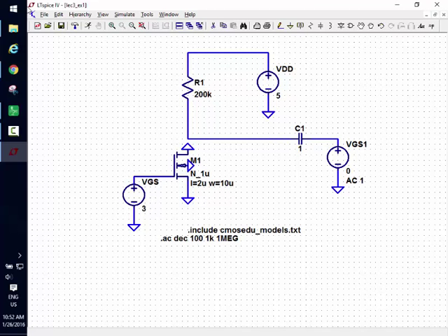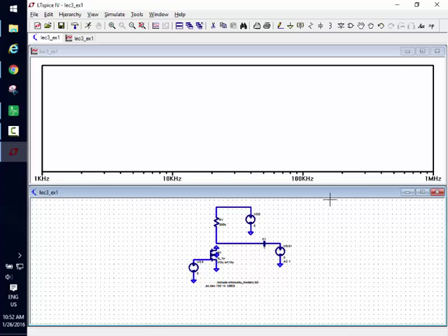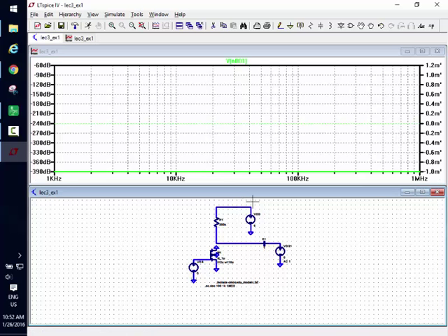All right, any questions on this circuit? What's that? Yeah, I'm going to leave the transistor out just to show I get 5 microamps flowing through here. Okay, so I hit run. First, I'm going to show the magnitude of the voltage here for AC. What is it? 0. Is that 0? Minus 390 dB is what? 0.000000001.